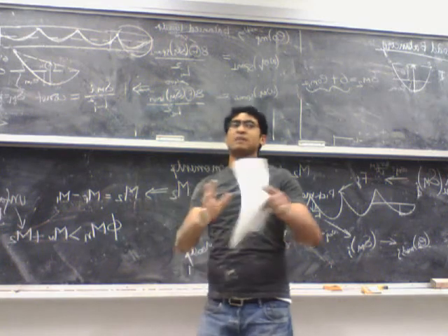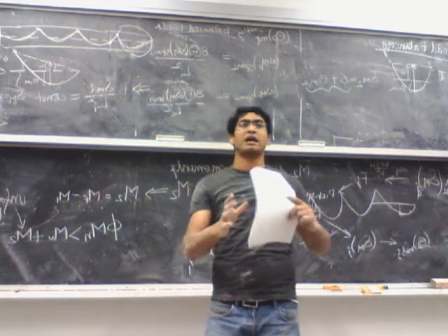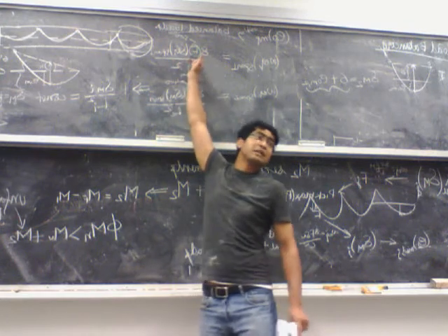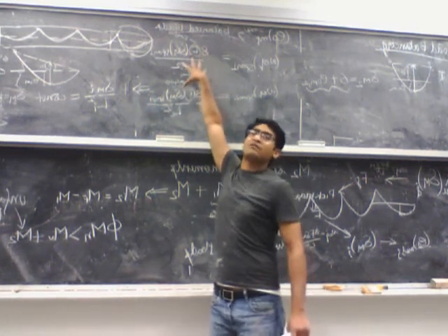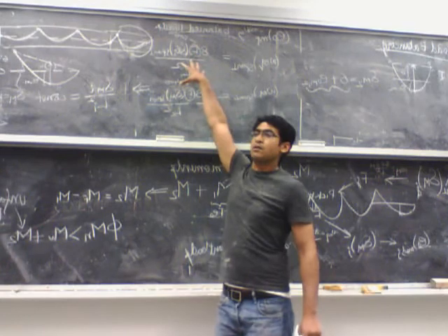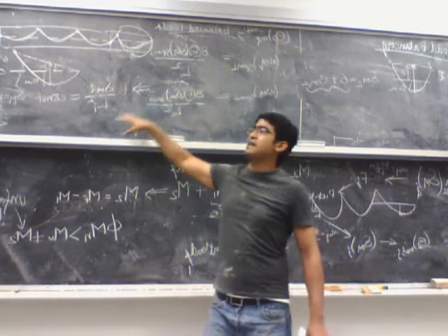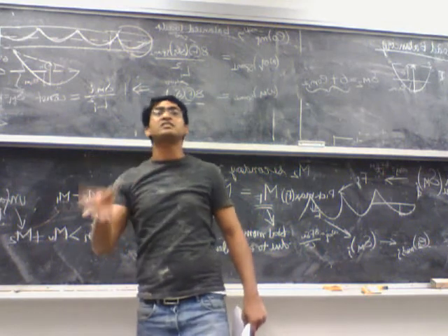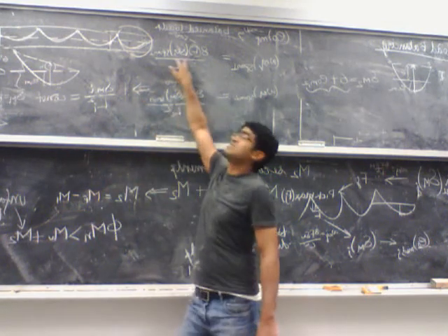So it might say 90% of so and so load is balanced by the effective pre-stressing force. Then this becomes F, that is eta times Fi. So whatever you calculate from this formula will be F. In the other case, it can say 90% of so and so load is balanced by the initial pre-stressing force. In that case, this becomes Fi.